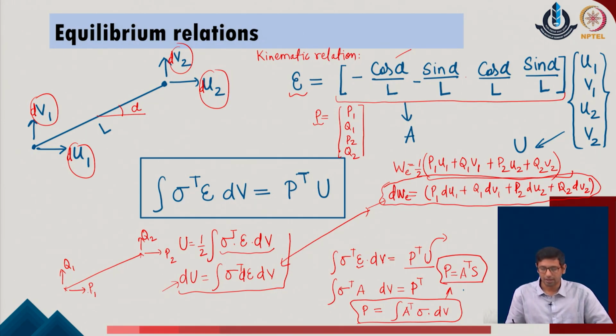Now, the point is that the relationship we have identified typically connects the nodal values with the internal stress components of the given system. And why does it become important? Because the increments which the user is trying to make will be defined at the level of the external loads on the given system, whereas the material behavior defined for the nonlinear response is defined at the level of the stress and strain relationship.